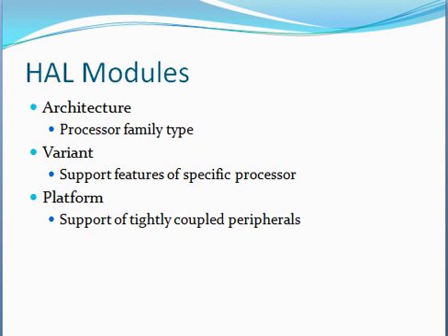Next, platform extends the hardware abstraction layer support to tightly coupled peripherals like interrupt controllers and timer devices. This module defines the platform or board that includes the selected processor, architecture, and variant. It includes code for startup, chip selection, configuration, interrupt controllers, and timer devices.